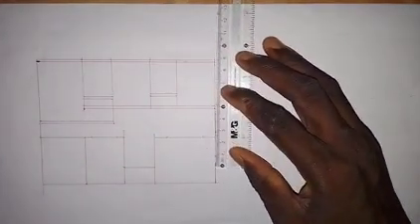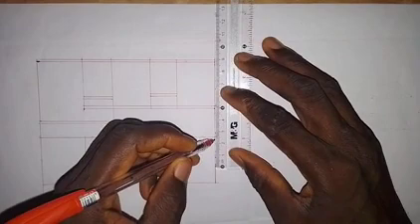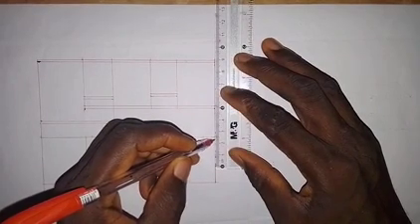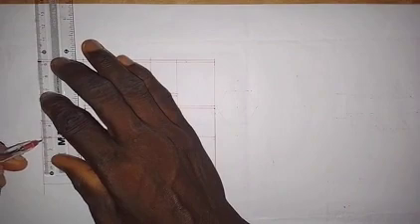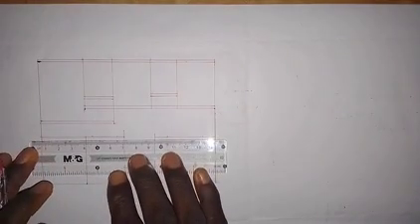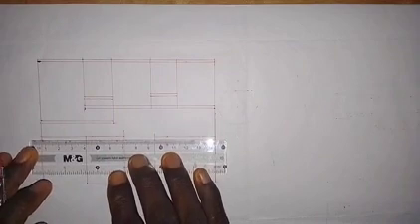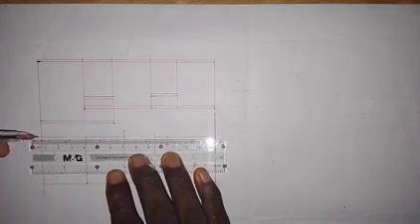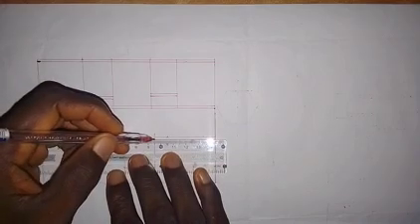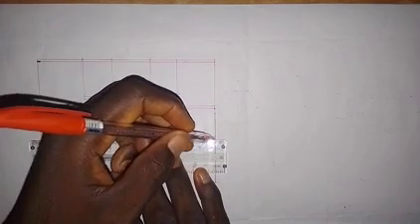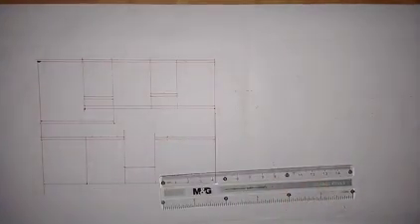Okay, so then coming to this one, here we take 2 millimeters inward. So this is 2 millimeters. And then coming to this end here, I will take 2 millimeters in. Okay. Then I'm going to draw horizontal line from here to here, and also horizontal line from here to here. Alright, so we have created the thickness of that wall.